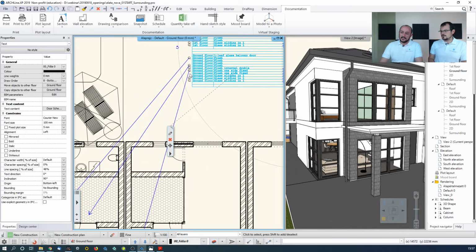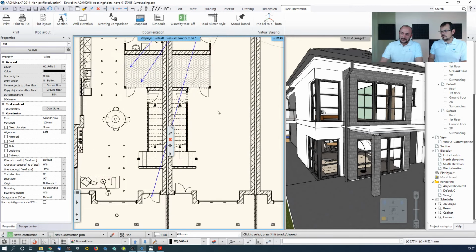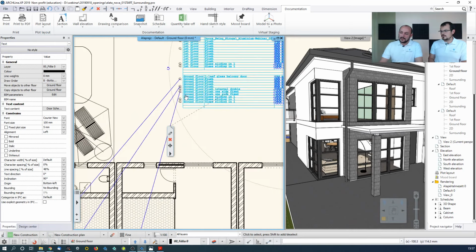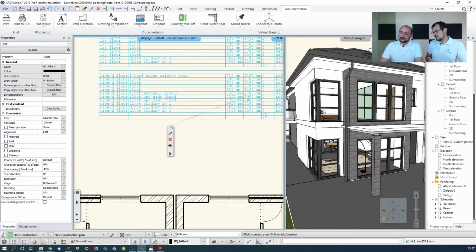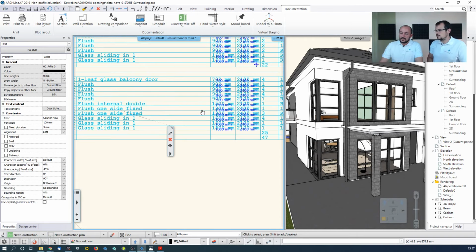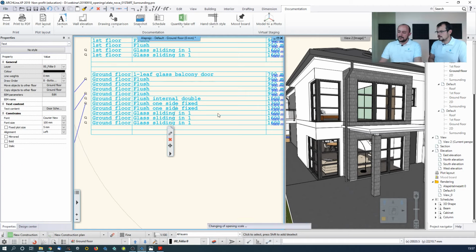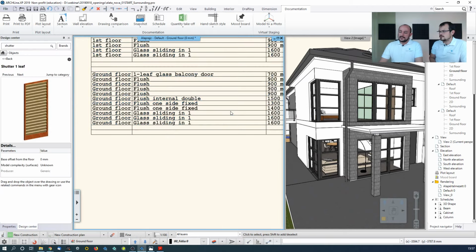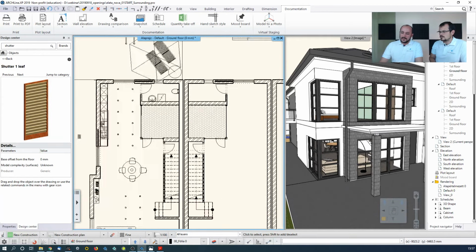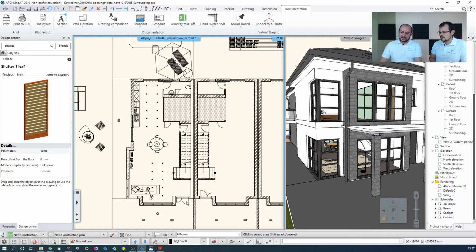So now this is what you can see. I'm just finding those doors and windows. And once I find one, let's say this one, let's say that you had a meeting regarding the project and you have to change that. So what do you do? In that case, I will change this value, which is, for example, 1,400. I hope there's enough space for that. It fits. So when I do that, it updates the list as well. I believe it jumped here, and then it also updates the drawing itself. See, now it updated the 2D as well.